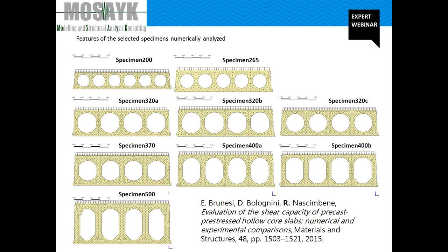In particular, let's focus on the fact that for the 320 mm slab, 3 specimens have been selected, 2 characterized by non-circular and 1 by circular voids to quantify the hollow core shape influence on the shear strength capacity for members with similar depth. Similarly, 2 400 mm deep units have been analyzed, since they evidence non-circular hollow core shape with various levels of irregularity.